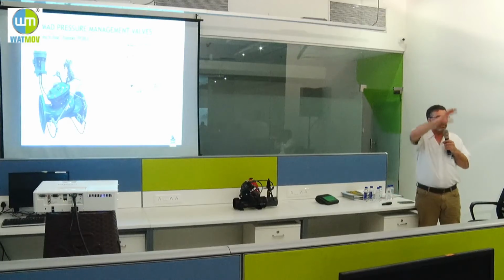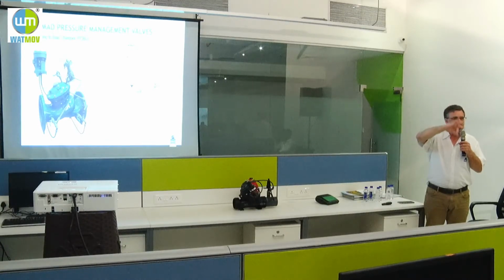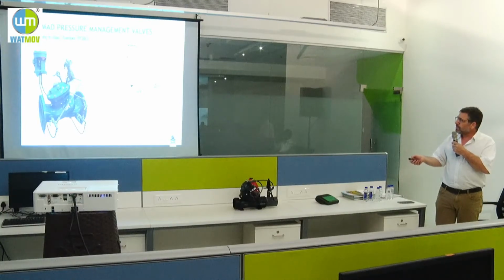We have the Barmat Cloud software, where I define whatever schedule I want. If I define that at 6 o'clock in the morning the pressure should be reduced to that level, and at 8 o'clock it goes to that level, and on weekends it behaves in this pattern, and on holidays in that pattern, everything is on the cloud. Then automatically when the time comes, the Delta, this unit, gets the information and changes the setting.